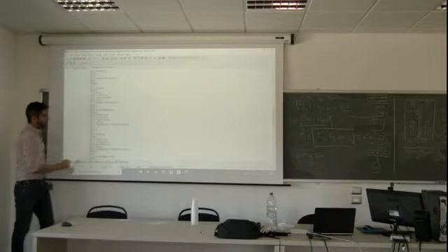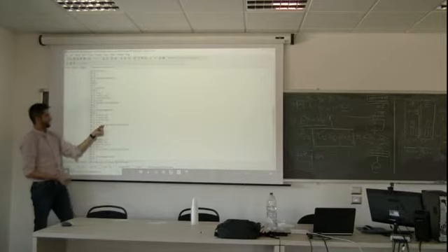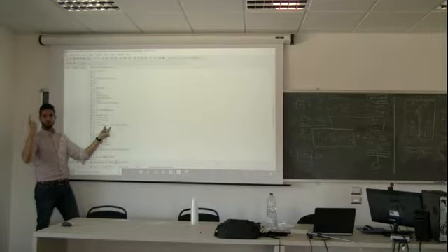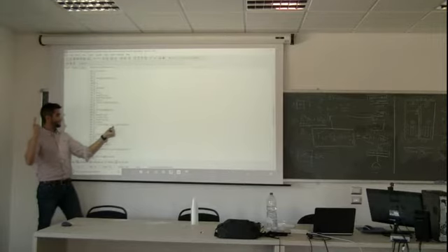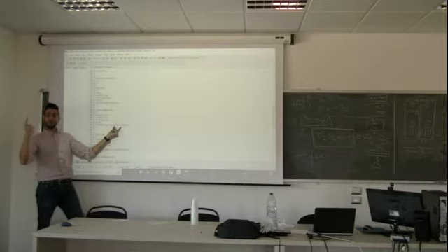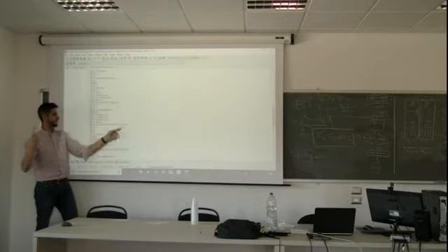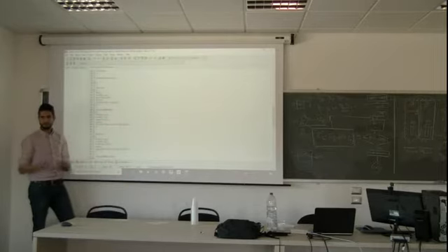The denominator will be B plus C, and my equation will be coefficient B multiplied by the past neighbor, the assumed value of T0, because we are at I equal to 1, plus a coefficient multiplied by the east node, the assumed value of node number 2 in this case, plus B, which is this term, divided by A.